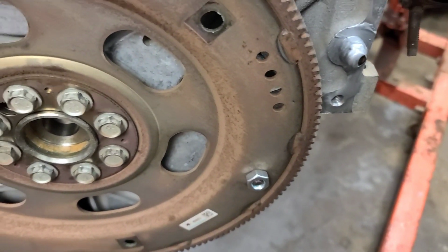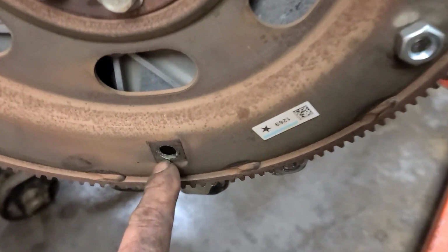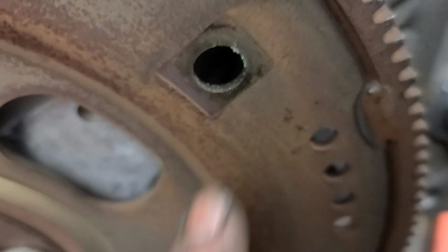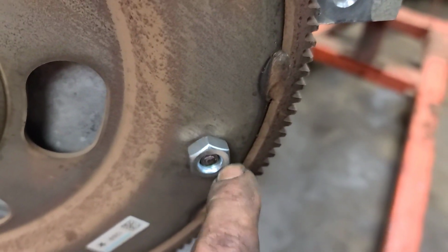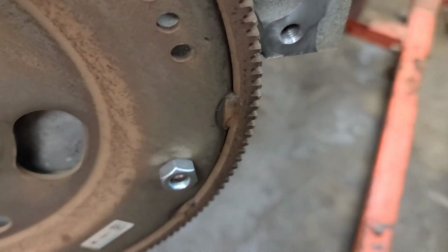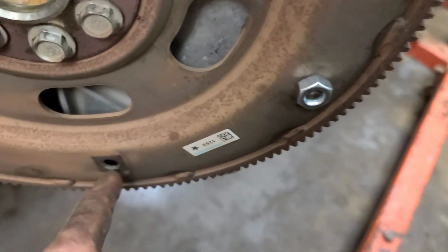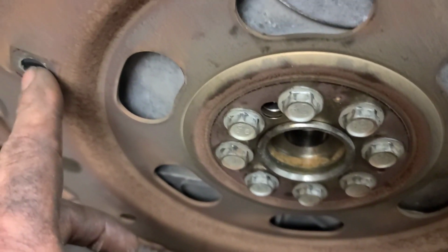And when you're positioning this engine, you'll see one of the holes is oval as opposed to round. Put the oval hole over here where the starter opening is, because that's the first torque converter bolt we want to start. That one will center the other 2 bolt holes.